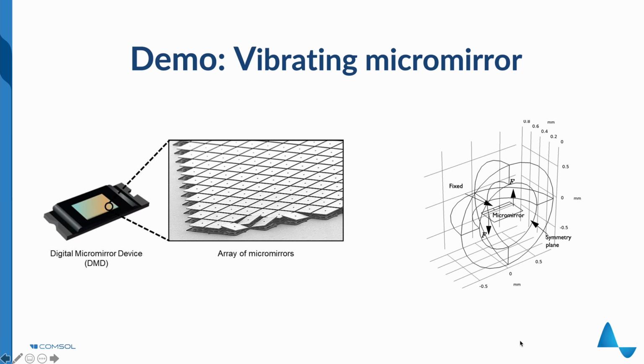The dynamic vibrating behavior of the micromirror, and especially the damping, is an important factor affecting the design of their actuator systems. In the development process of new micromirror systems, modeling the damping correctly and thus predicting the performance of the system can save both time and money.